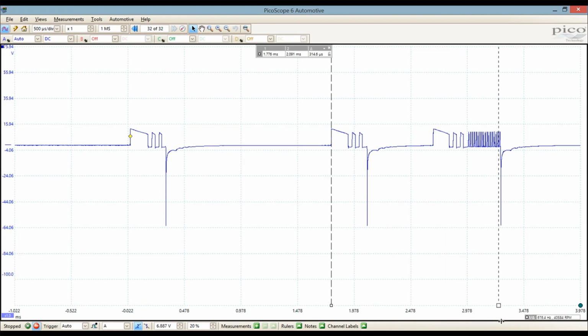The main injection pulse is 605 microseconds, or 0.6 of a millisecond. Some CRD engines remove one pilot injection pulse as RPM increases. This more precise control of the injection process helps to reduce noise, produces lower emissions, and gives us better fuel economy.